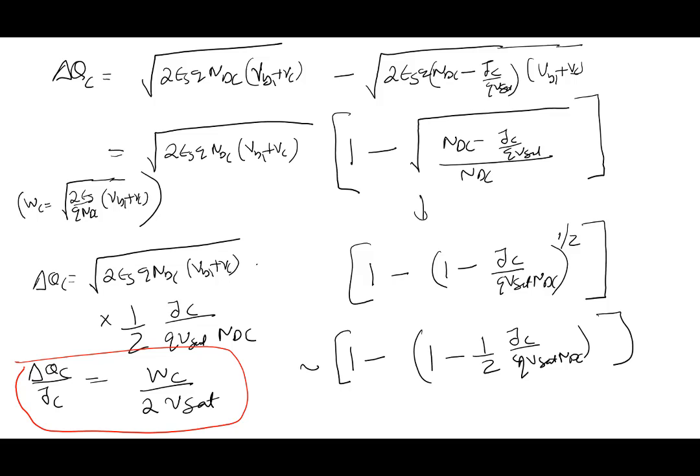Note that it's interesting that all the mobile charges, when you divide them by current, all come out to be a constant term. It's independent of current density. All mobile charges give rise to a delay which is a constant. And all fixed charges, depletion charges, give rise to a delay which is inversely proportional to the current density. So a simple derivation of how much charge there is in the collector depletion region, and the delay that it will result in.